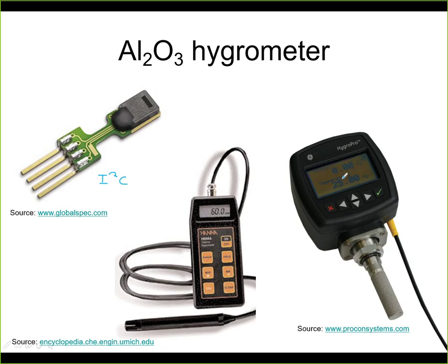Here it shows you the humidity, no, this is temperature in both cases, but it's a hygrometer sensor, and it also has an output signal. So here on this cable we'll have the data about the humidity reading. It can be operated also as a handheld instrument, so like this. So here you see this slot. This is actually the opening that allows the air to enter into the sensor. The sensor will be somewhere around this place.